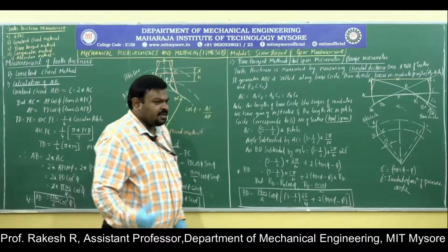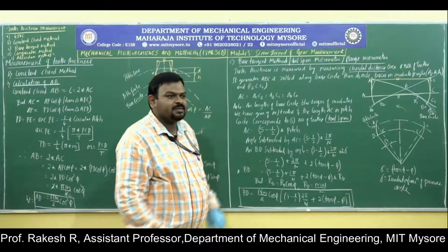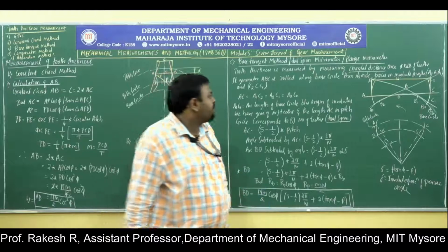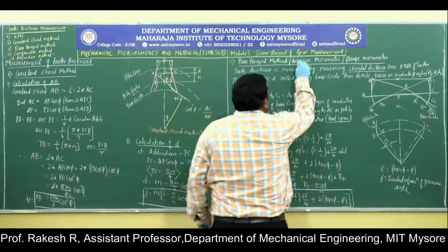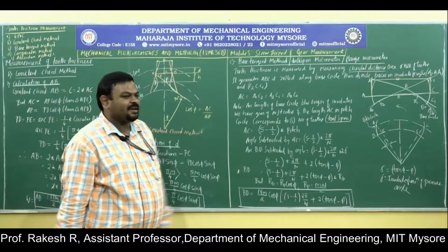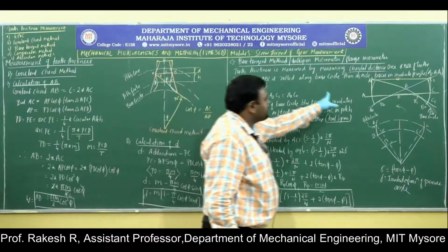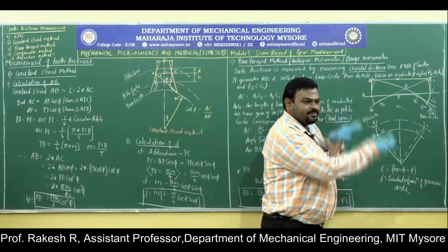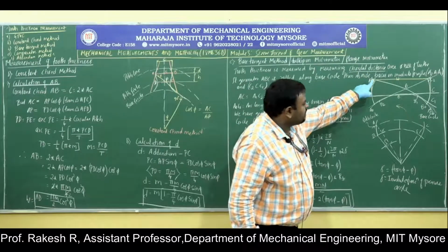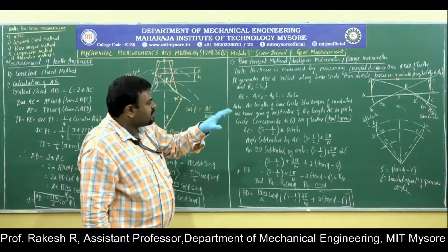And here it is not only applicable to one tooth, it is applicable for a number of teeth. Hence the name span comes here. Tooth span. It is not tool. Tooth span. We are using a tooth span micrometer, that is for a number of teeth. And the straight generator ABC is rolled. As I already told, it is being indexed, rolled along the base circle. Then its end traces an involute profile.